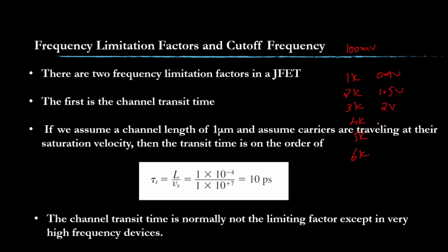Okay. So just assume the cutoff frequency is equal to 4.5 kilohertz. Till 4.5 kilohertz you are getting better performance, 2.5 volt. But when you increase the frequency above the cutoff frequency, your output amplitude is going to reduce again to 2.